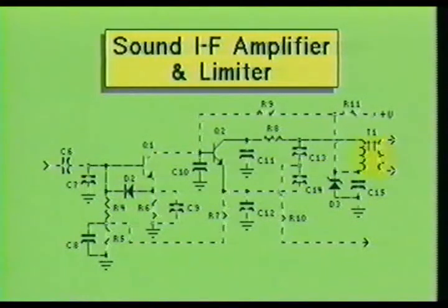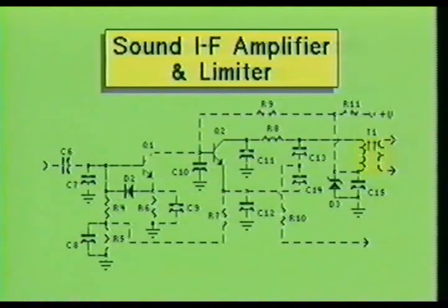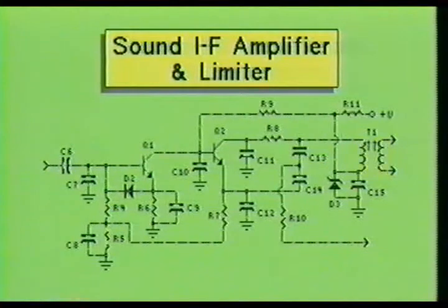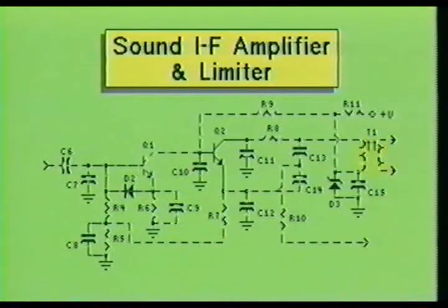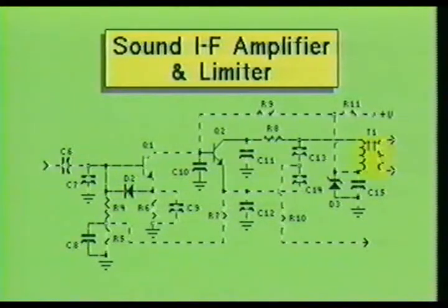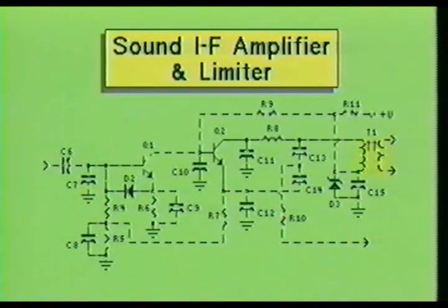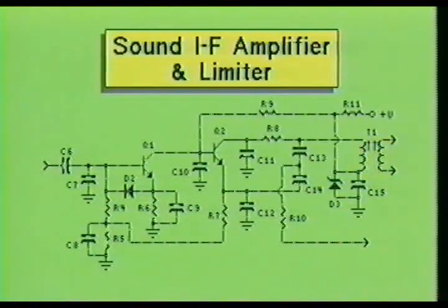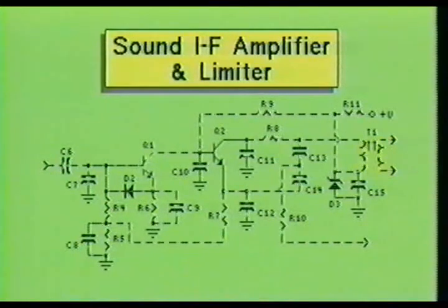As you can see, when transistor Q1 conducts, a lower voltage level appears at the base of transistor Q2, which biases Q2 off. Current rushes from ground and passes through resistors R5 and R7, bypassing transistor Q2 and charging capacitors C13 and C14. The current flows to the primary winding of transformer T1 and through resistor R11 tied to the positive potential.